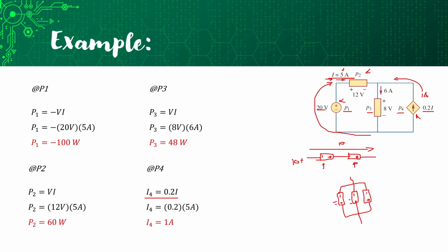But voltage divided means, for example, we have 10 volts here, positive 10 volts. Assuming that the resistors here have the same value, the voltage is divided, so the voltage in this resistor is 5 volts and also 5 volts in the other. This is what we call a voltage drop: it drops 5 volts here and drops 5 volts there. That is why it is called voltage divided in a series connection.